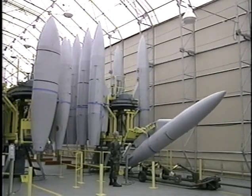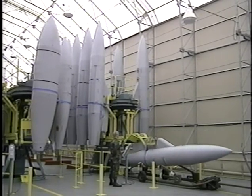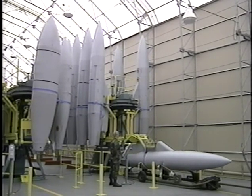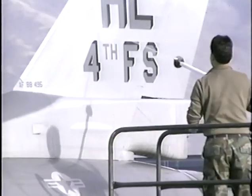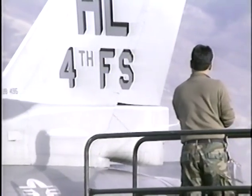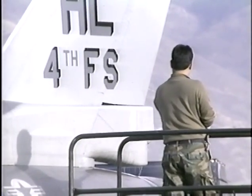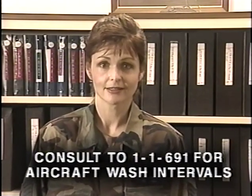Fuel shop, as well as weapons personnel, should be aware of the corrosion associated with external mounted aircraft accessories. Sway braces and other hardware used for attachment purposes are often the center of corrosive environments. Two of the most important preventative measures are quality aircraft washes and frequent wipe-downs. The cleaning schedule of an aircraft should be tailored to the environment in which it is operating.